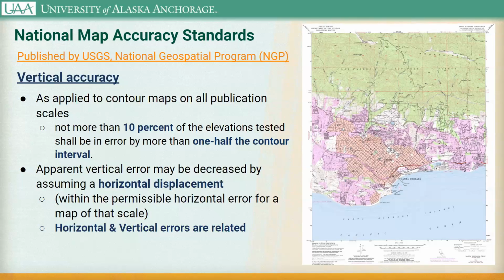That's a pretty common issue that we see in measuring shorelines, for example. It might look like your shoreline depths are all too deep or too shallow by a foot, and really what it meant was that you shifted your slope horizontally in the wrong direction, and it looks like a mirror of the correct slope in a different place. So I hope that makes that clear to visualize.